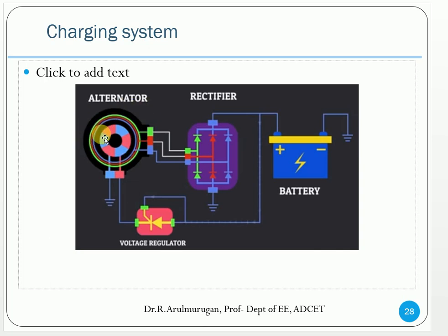Generally a generator has two parts. One is a stationary part, okay, the coil is coming outside. The second one is the rotor, the rotating part. To that rotor, a prime mover is attached, and with the help of it you give DC excitation. So why DC excitation? Because it is going to produce a magnet. So the prime mover is attached to that rotor, so here the field is excited.